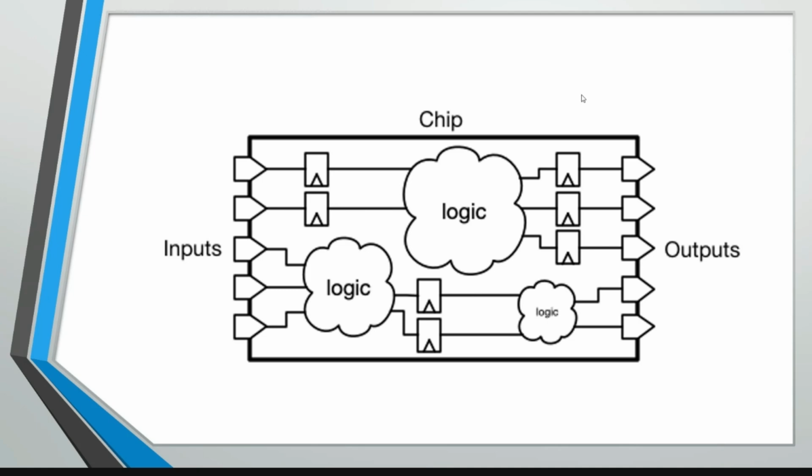These flip-flops are already connected to the logical gate inputs or outputs, so you can control a particular flop to load our desired value. A logical gate can then be tested for 0 or 1 as per its truth table behavior. DFT is going to insert this additional mechanism for controllability deep into the IC at each and every logical gate.